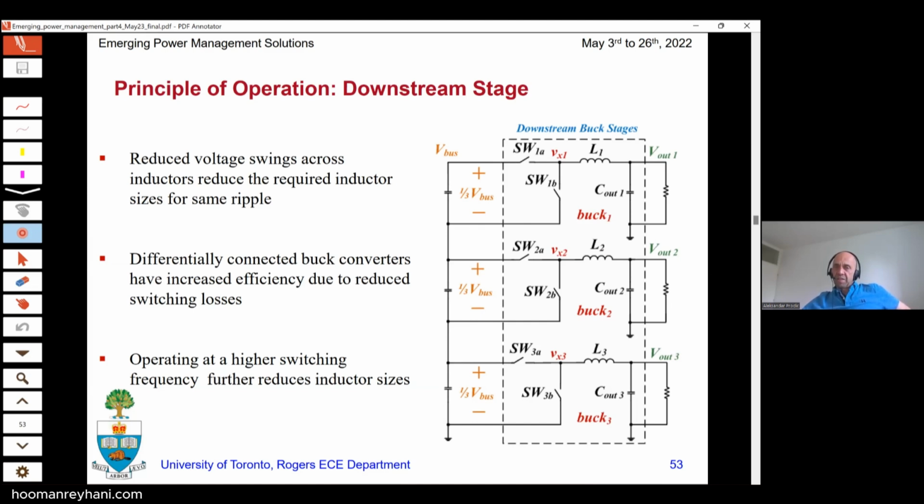For example, this is a high voltage output, then 3.3 and 1 volts, and depending on the output value, we can put as a front-end stage something like a capacitive divider, and we will see soon that it is actually a switched capacitor converter. And then rather than switching between 0 and full bus voltage, we can switch between these types of voltages.